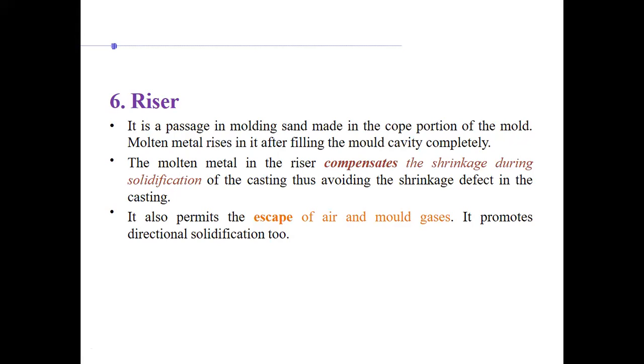We've discussed three types of contraction, right? Basically liquid, liquid to solid, and solid contraction, what we have discussed earlier. Liquid contraction is when it is contracting while in the liquid state. Liquid to solid contraction is while it is contracting when it is converting from liquid to solid, right? And the third one is solid contraction, when it is completely solidified, then also it contracts. Complete solid contraction we can call it.